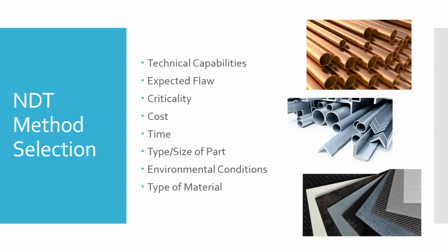I think spray cans are about $20 to $50 a can, which sounds like a lot, right? But you need 3 cans, okay? So you're talking $100 for the equipment to do dye penetrant inspection. An eddy current tester starts somewhere in the $10,000 to $20,000 range. It can find even smaller flaws, but you also have to consider the training. A lot more people are trained and competent at liquid penetrant than eddy current. You'll see the difference when we do both of them.